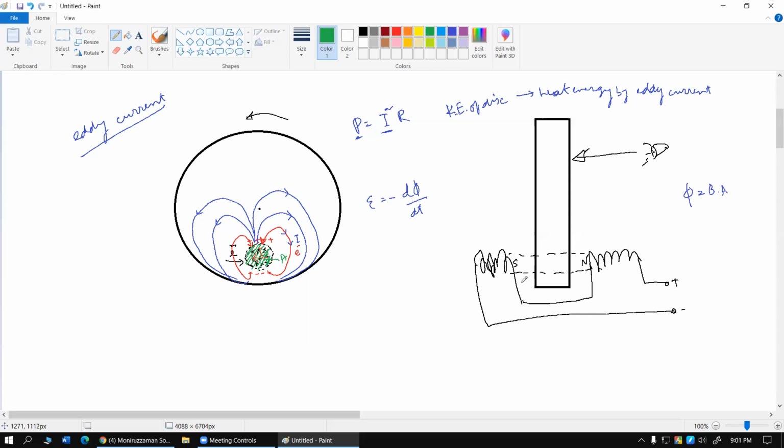The third way is that if we increase the area itself. So for example, other than using this small area, if we use a bigger circle, or these two coils are made even bigger, we're going to start to lose kinetic energy even more rapidly. And not only that, we can also produce this eddy current, or the rate of kinetic energy conversion, even more rapidly if we introduce multiple solenoids across different parts of this disk.